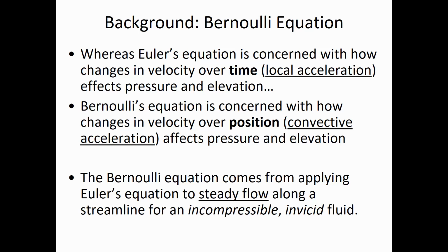Okay. Now, these last 2 is where things get really interesting, because what we're saying is we really only ought to apply Bernoulli's equation if the liquid in question is incompressible. So what kind of fluids are incompressible? Because remember, there's gases and there are liquids. Both of those are fluids. So fluid is the more broad term. Fluid mechanics includes gases and liquids. And so between gases and liquids, which are incompressible? Liquids. Okay. So we're saying, all right, Bernoulli's equation should be used for liquids.